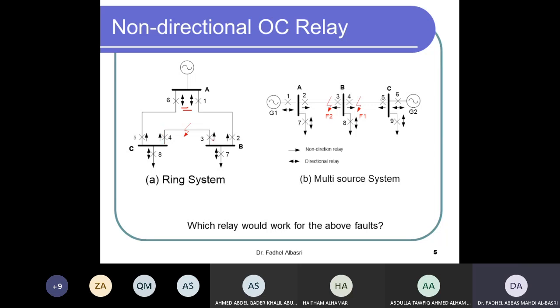Okay. This is also this. This is same. So this has to be direction, the tripping direction, always facing each other. This should be non-directional. No need for at 1 and 6, no need in this case. Similarly, if I have a breaker here, okay, no need to be directional, so it could be non-directional. Okay.